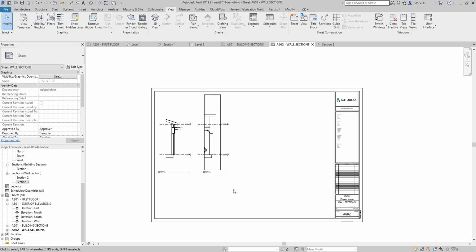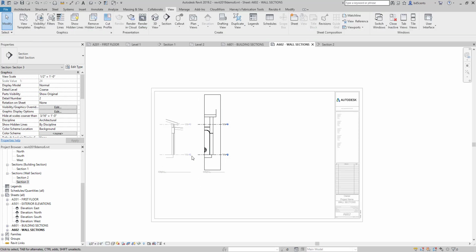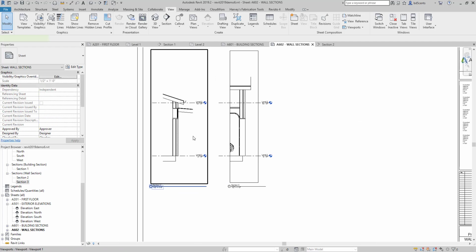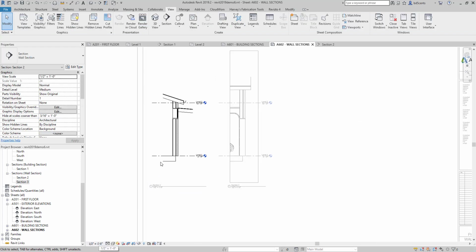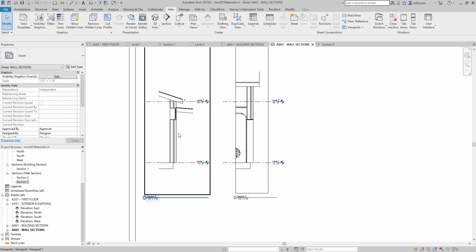The Revit scale change selector at the bottom of the screen allows you to adjust the different views on the fly. So I can double click in, change the scale, change the quality to be medium so that I can see more detail, and double click out. So it's important to understand that these values adjust the scales of these views. And these are actually aligned. This is the front door.